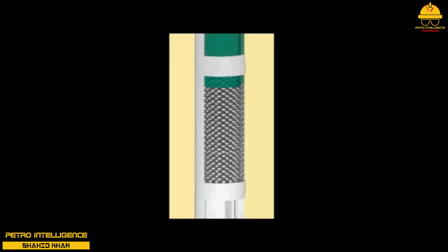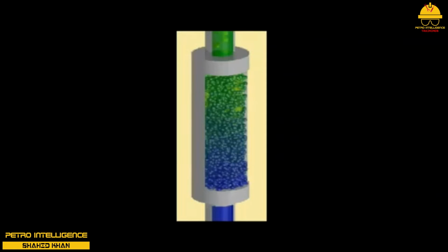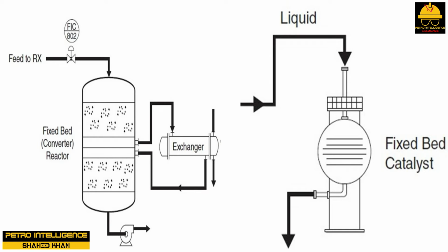process fluid. Fixed bed reactors are designed with an inlet line and an outlet line, catalyst bed limiters, distribution and support grids, catalyst removal hatches, process variable instrumentation, and safety systems. Many converters have a method of removing or adding heat from the bed. The main reasons for arranging the packed beds in a configuration other than the large single bed are to provide better heat transfer, to provide better distribution of the reaction mixture through the converter so that the gas or liquid feed will not channel through the bed, and to reduce the amount of force applied to the packing at the